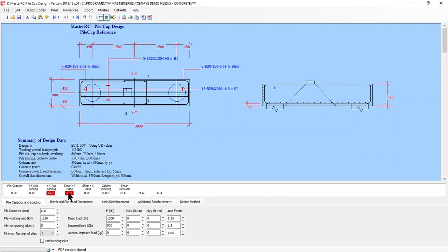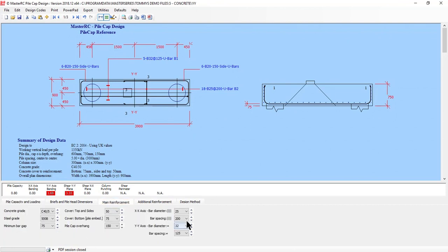for design. So if this was required, obviously what you would be looking at doing is putting in an awful lot more reinforcement and seeing if that improves it. So we're still, and it's not really the bending that's the problem, it is the shear. As you can see, if we went up to 40mm bars, we have no bending problem, but we still have this shear problem.